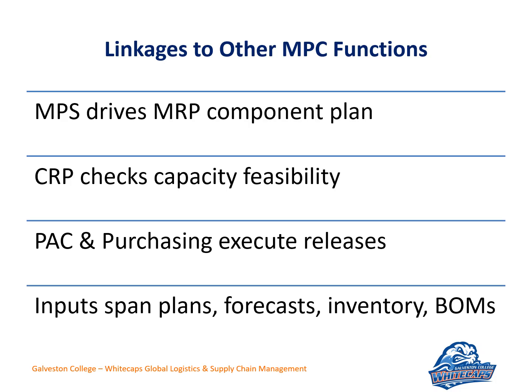So we also asked, what does it link to in the other MPC functions? Well, how do they all link together? The master schedule is the engine, right? And the MRP translates the end item plans into components. What needs to be built when. The capacity planning verifies that machines and labor can meet these needs. So you've got to know what we're capable of doing on a daily basis, and if there are delays popping in and out of the production schedule.